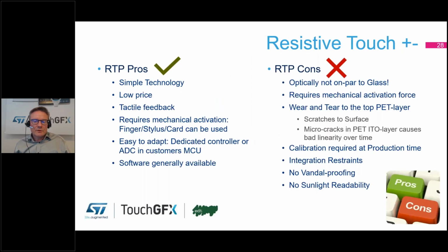today we do run more and more into capacitive, and the reason for that is, if you look at the con side of the resistive technology, you cannot compare resistive technology with capacitive technology in terms of optical performance or look and feel. It's simply not on par.